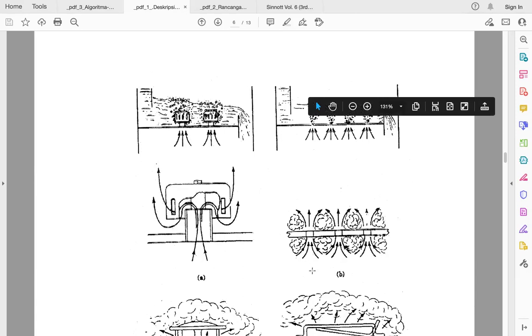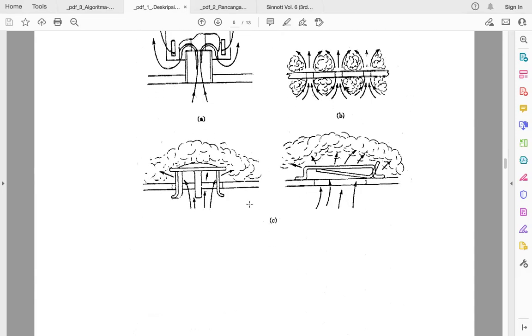So the composition of the vapor just goes straight through with the composition of the vapor at the bottom, while ideally it should contact the liquid first, and then leave with the new composition.